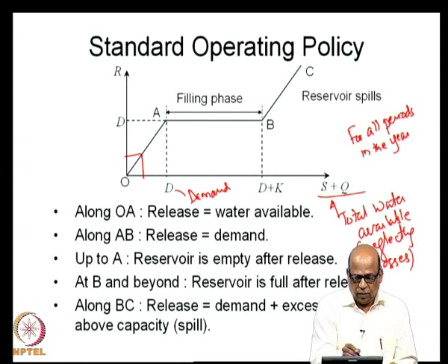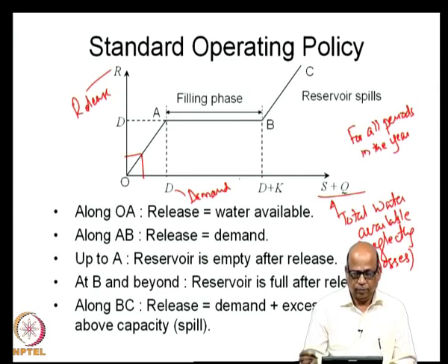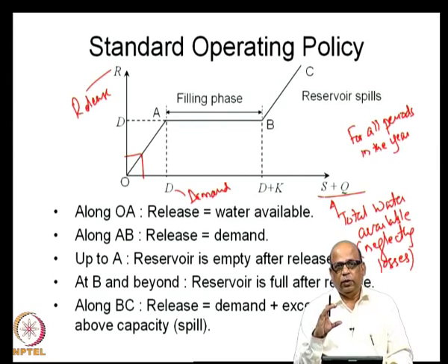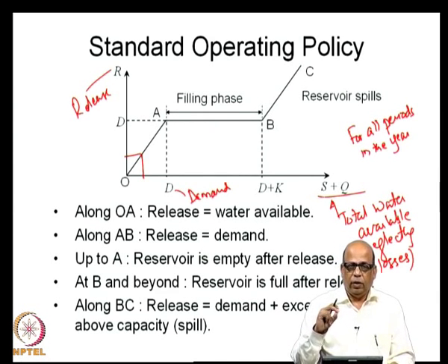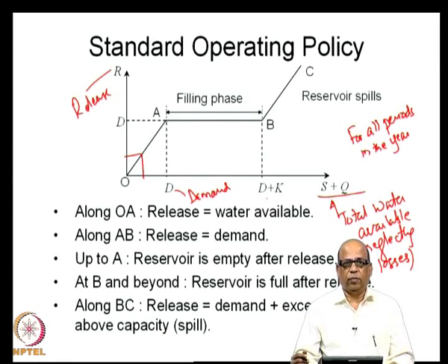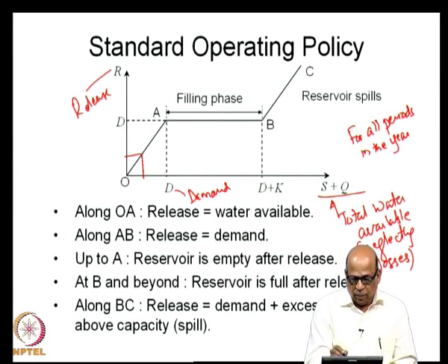You keep on making the release D only, equal to D. On the y axis is the release shown. So, we are saying that release will be equal to D whenever your total water available is greater than D. So, the reservoir starts filling up. Until what time does it fill? Until your S plus Q, which is the total water available after you meet the demand D, is greater than the storage capacity. So, until D plus K, which means this is the storage equal to K.